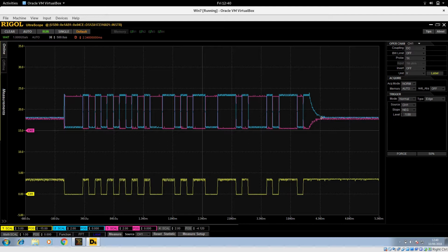And like I say, most protocols now use that, apart from LIN bus is one I can think of that doesn't, but most protocols use this because if we have a voltage spike on this serial line, then we can potentially interpret that as a start bit, and then we receive a byte of data that was never transmitted.